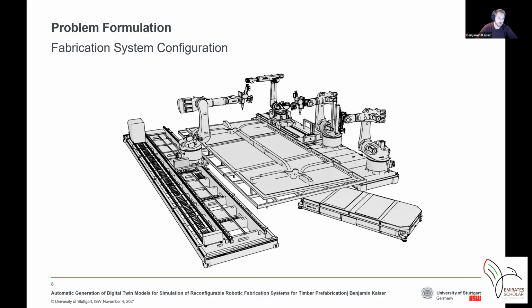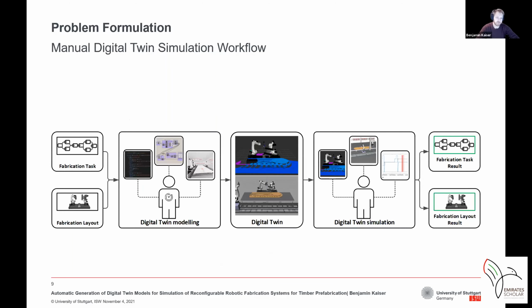However, in robotics, normally we have the problem that it's not possible to solve these problems entirely on this abstract level, because at the end we need to also check at some point the inverse kinematics and the robot dynamics. Maybe also if we, for example, want to pick and place a large beam, then we definitely have to consider collisions while moving along a certain path.